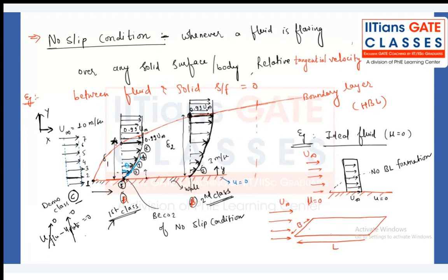That means whatever the negativity is there, that negativity is getting spread like anything among these students, each and every one after the class. So now to attain the same 99% of the free stream velocity, the fluid particle needs to travel more distance or what? See, the third particle is getting slowed down. Earlier it had 4 meter per second, and now it is 3 meter per second. So slowly it is gaining its velocity in the y direction. So definitely to achieve 99% of the free stream velocity, it has to travel more distance or less distance?